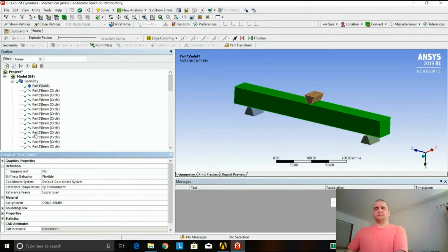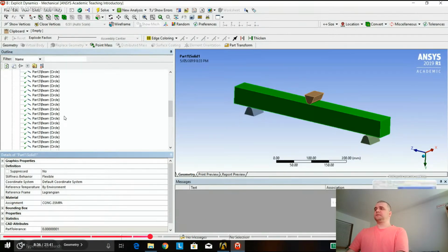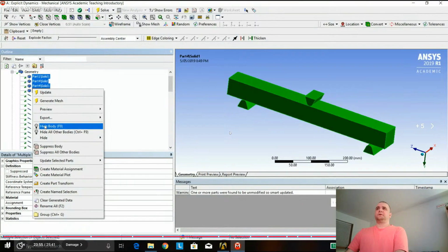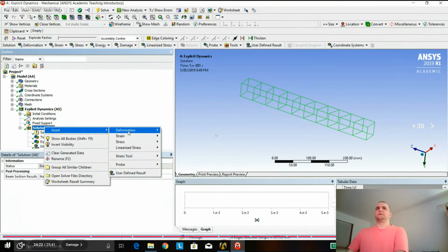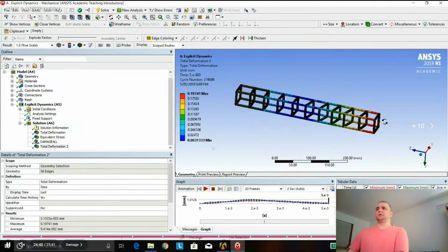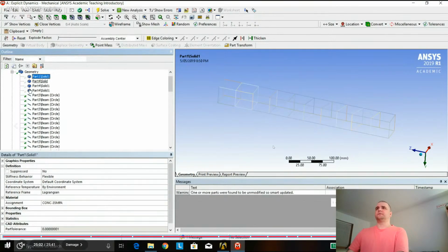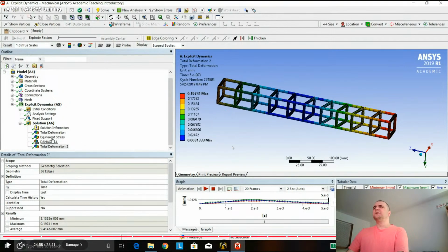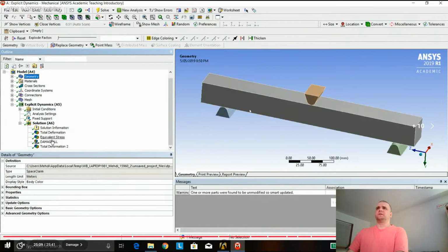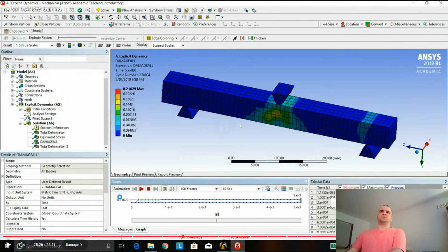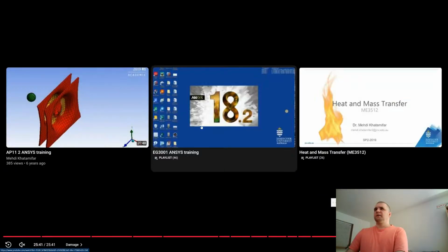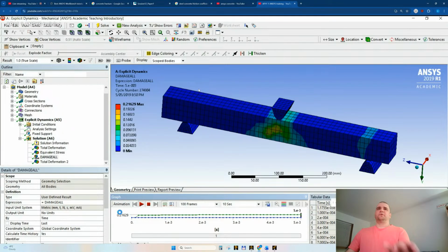The concrete that I'm using, yes, from explicit dynamics. Too bad he does not know how to put proper boundary conditions. Yes, but maybe in the future, maybe he improved. After this point, maybe he improved. So fine mesh here and coarse here, and with no proper justification. Yeah. This is why the solving took 45 minutes or something. I hope he improved.